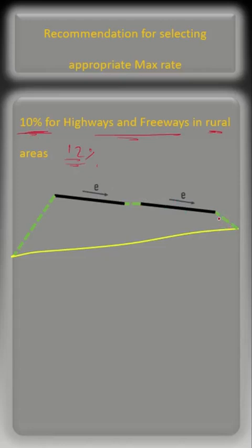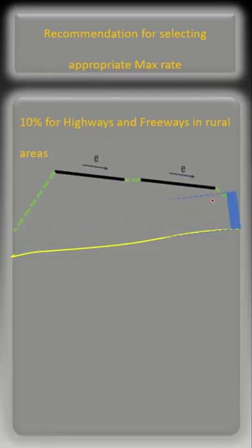For instance, using high superelevation rates may make it difficult to provide enough height for culverts unless we increase the embankment height, which costs more and it's also not desirable safety-wise. So there are situations selecting 8% as maximum superelevation rate becomes more appropriate even for designing highways and freeways.